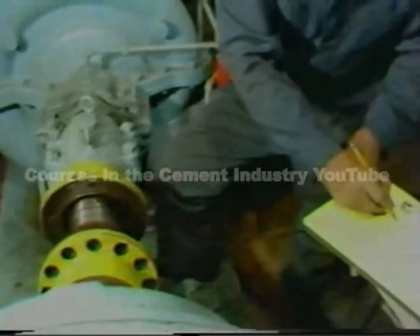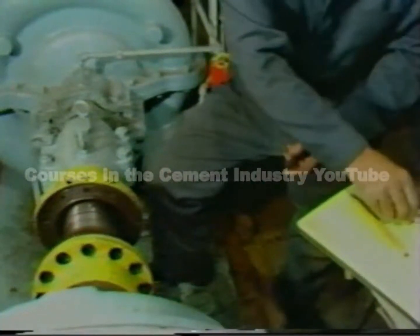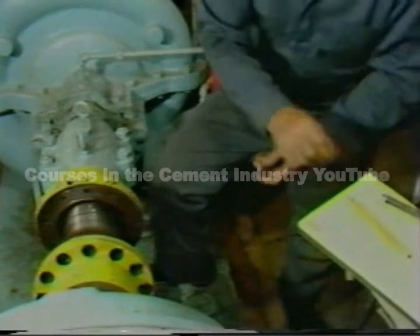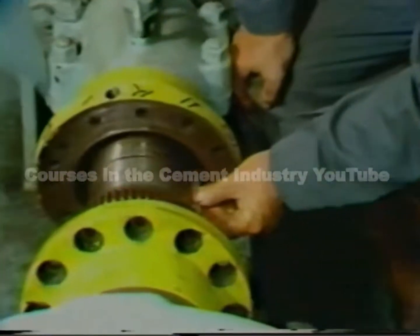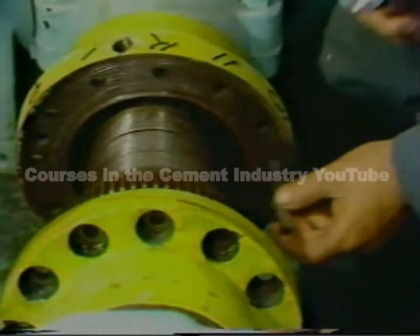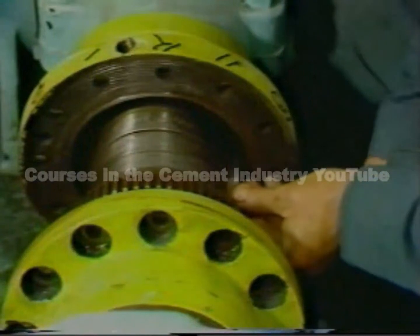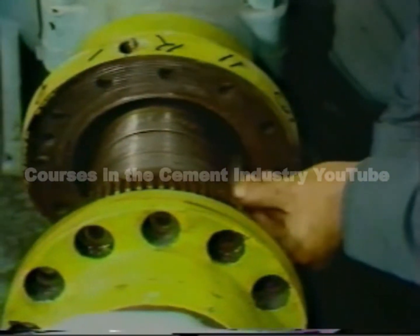How do you make this measurement? Well, one way to determine that some amount of offset exists is to use a straight edge. By placing the straight edge across the two coupling halves, a flashlight can be used to check for a gap indicating some offset.